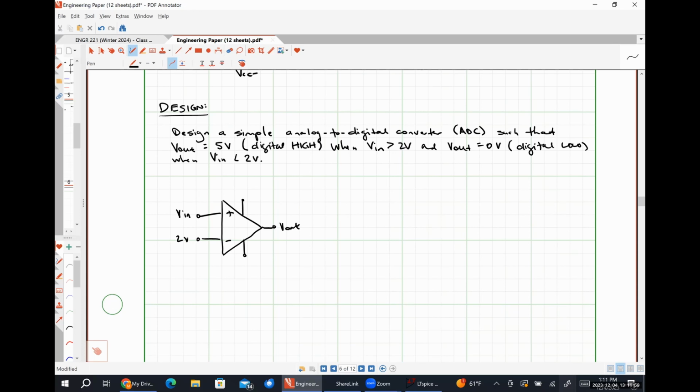All right. So what do my supply voltages need to be? 5 and 0. Which one's which? It's kind of obvious, but 5 volts has to be VCC plus. Put ground as our reference. Congratulations, you guys have just designed your first op-amp circuit. Just as a heads up, this is exactly how the analog to digital converter in your Arduinos works.